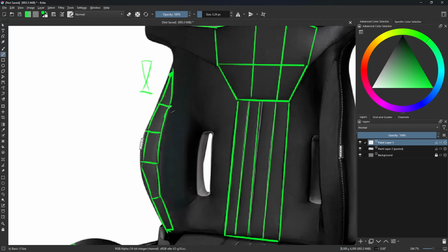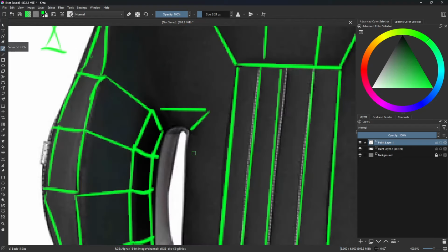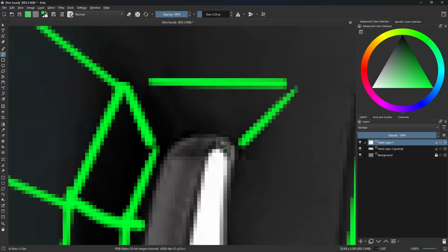You don't go straight to the most complicated things necessarily. Sometimes you have to, but you'll find a balance for this. And so a lot of people just ask, how do I learn how to do this? Well, start practicing on basic models like this, right? If you see a chair and you want to model this thing out, start thinking about how you're going to lay out that topology, how it might actually work out here. So you'll realize we have these really small curves in here, right? And if you want to model those, you're going to end up needing 3 edges for that.